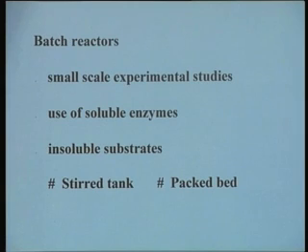So, you need a pump. Similarly, at the outlet you also need a pump to withdraw the product stream, whereas in the case of a batch reactor, you just initially charge the reactor and continue under reaction conditions, and then discharge the reactor at the end of it and do the cleaning operation. So, no supporting structures are required, and therefore, they are very simple, and find a very common application in small scale experimental studies.